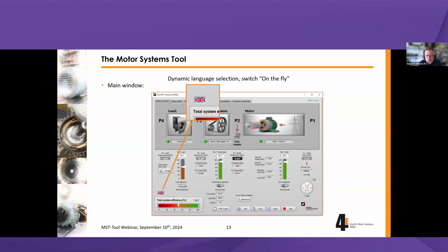I should also mention, by the way, if you can see on the main window now, we have basically a calculation of the actual duty point with a 90.7 efficiency of the transmission, which leads to this power. And by the belt, we have a ratio between the speeds, so that would be 1745, and those two calculated together give this torque into the load, and we have an input efficiency on the load of 62 in this case, and therefore an output power. So we have the entire chain visible at the main window in an instant.